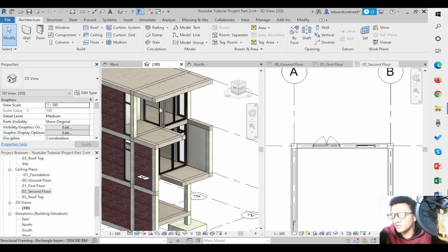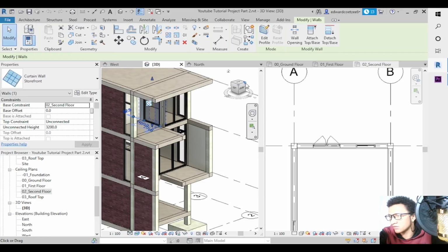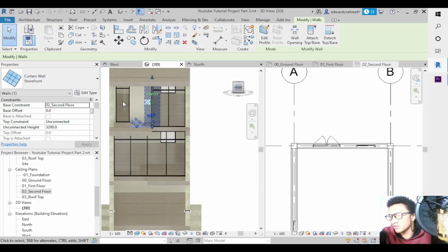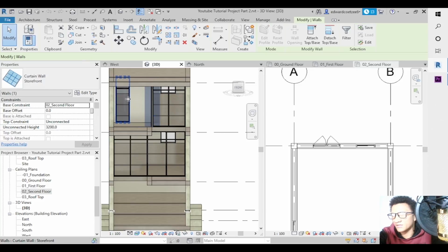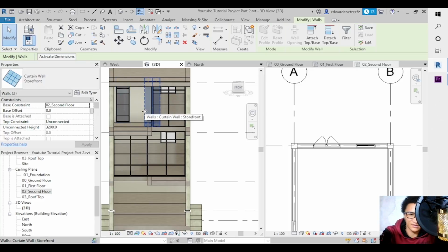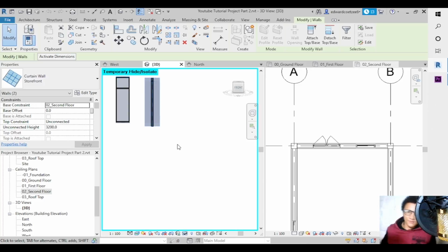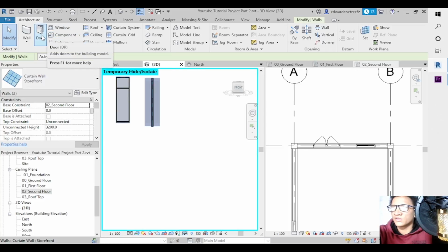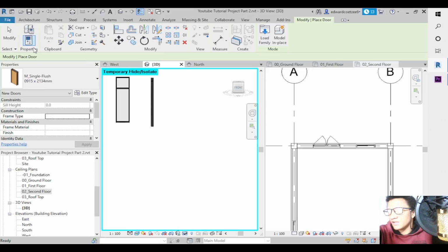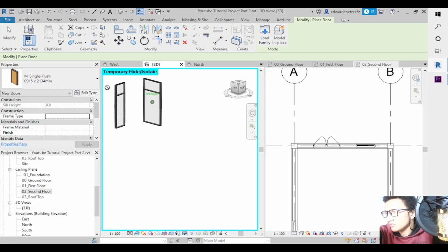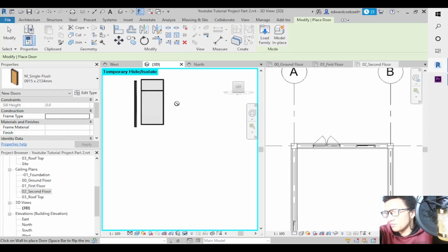Oh, before we insert our railings, let's just quickly throw in some mullions on these ones. So what I want to do is I want to select those two windows. I want to go HI. Okay, so basically I should have only highlighted this one because I don't have it. The door families, there is a way to import your families for your doors. Let's just say I should have imported a door, a glass door. I don't have a glass door now, so what I want to do this side is I want to insert a mullion as well.